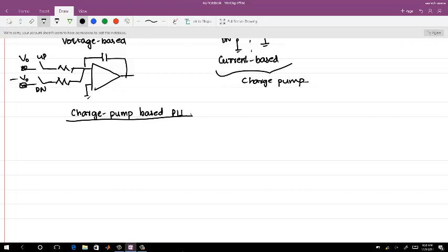When we derive any of the gain characteristics, we are looking at what should be the average value when things have been locked. I think the confusing part is that I am always using the average value of the PFD output to show you the gain characteristics. But that does not mean you don't need to average physically in a circuit. That's the difference. Does that clear things up?